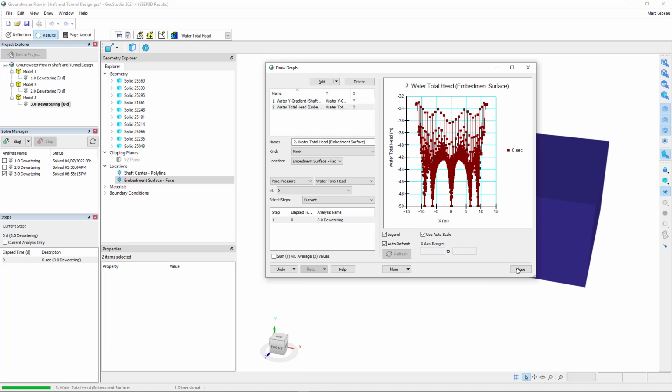We can now focus our attention on the stage-constructed tunnel for which the internal components, or future voids, appear as meshed items in the domain. This is paramount as it provides the same mesh in all parent and child analyses. As will later be shown, the material assignment can be removed from the relevant solids during the tunneling process.